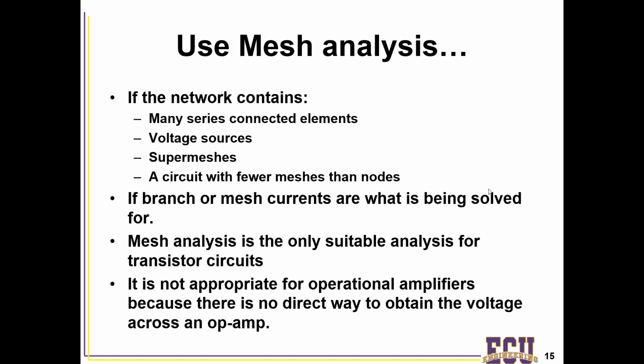And it's the only suitable analysis if you have transistor circuits. We're not going to do a whole lot of solving of transistor circuits, but just keep in mind that nodal analysis doesn't apply. It's primarily based upon currents going in different directions, and so mesh analysis is going to be the only analytical technique for transistor-based circuits. This is not going to be appropriate once we start getting into operational amplifiers, largely because obtaining the voltage across an amp is particularly difficult. So once we get into op amps in Chapter 5, we're going to hone in on some analysis techniques, primarily using nodal analysis in that case.